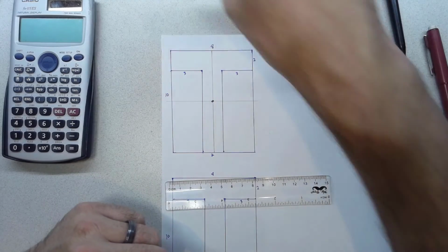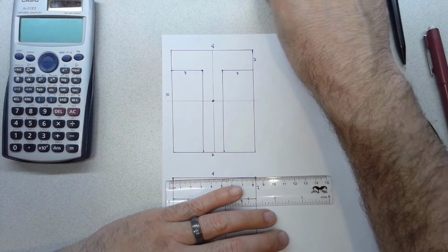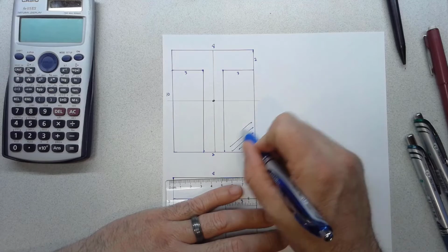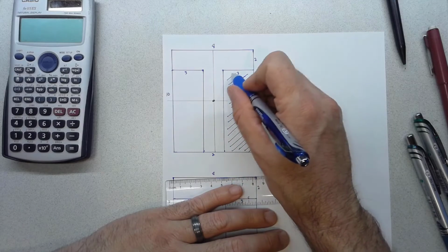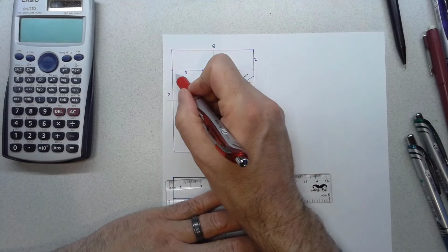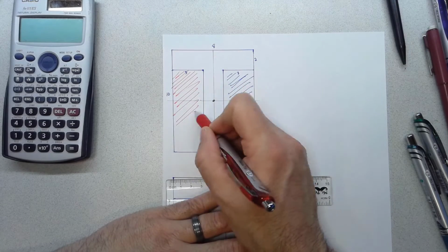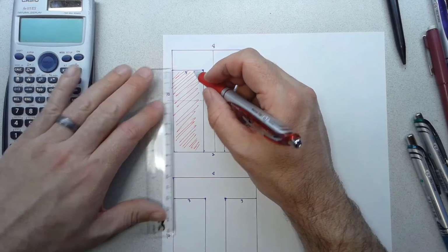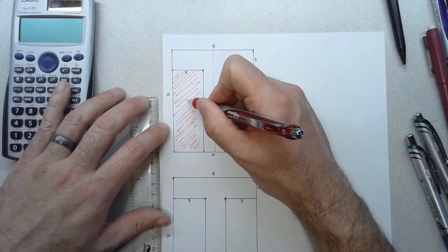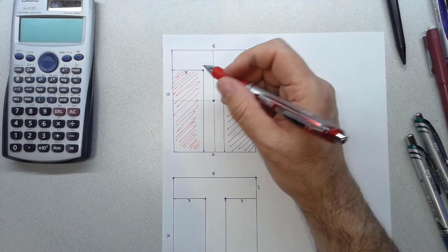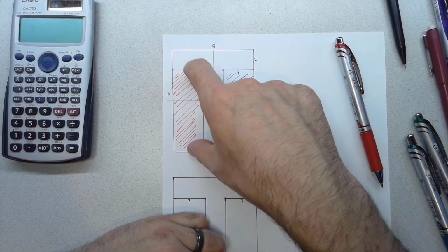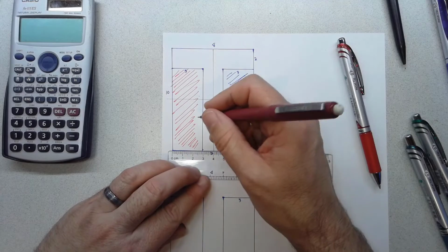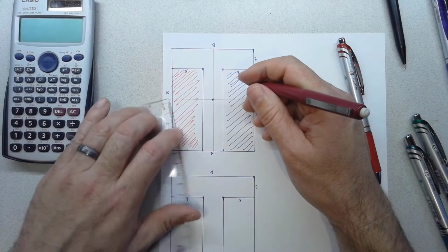Let's look at that a different way. The T that's left, we're going to create by removing that chunk, and we're going to remove that chunk. So where are the centroids of those 2 pieces? They're going to be over 1.5, right? Because we're at 3, so they're going to be along that axis. But this is 2, so our height here is 8. So let's come over 1.5, and then up 4.